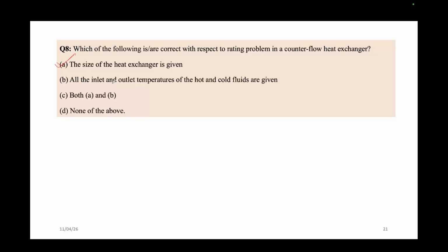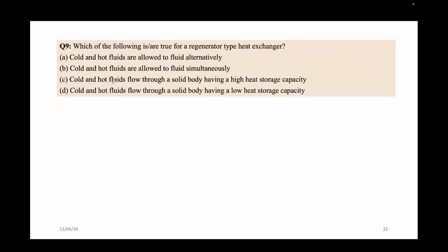But remember one thing: a rating problem in general may be area rating or power rating. But in the general scenario, if it is talking about a counter flow heat exchanger, then rating problem means power rating, because the NTU method is good for counter flow heat exchangers. Can I move to the next one? From heat exchangers, this is the last question. So please try to answer.